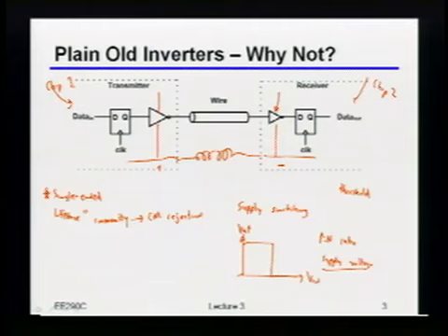You don't have the termination, right? Okay, that's right. I don't have any termination. That's really bad. That's true, and actually you'll see in a homework exactly how annoying that is. There are certainly a lot of issues related to not being terminated. By the way, this particular thing may not be correctly terminated on the transmitter nor on the receiver, right? So it is certainly true there's going to be a lot of signal integrity issues because of that.